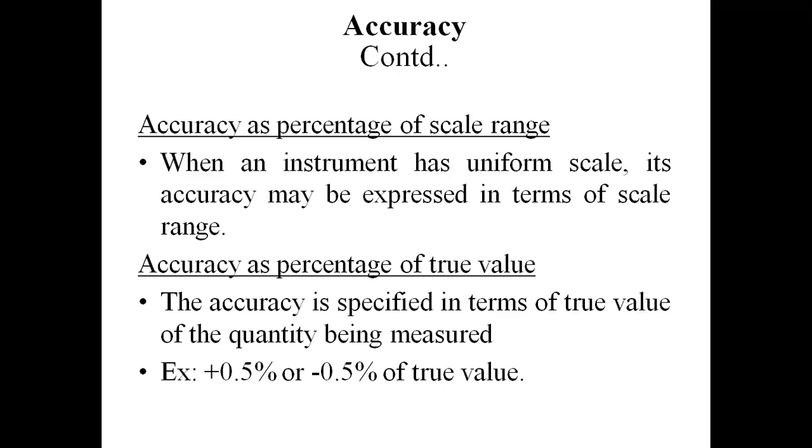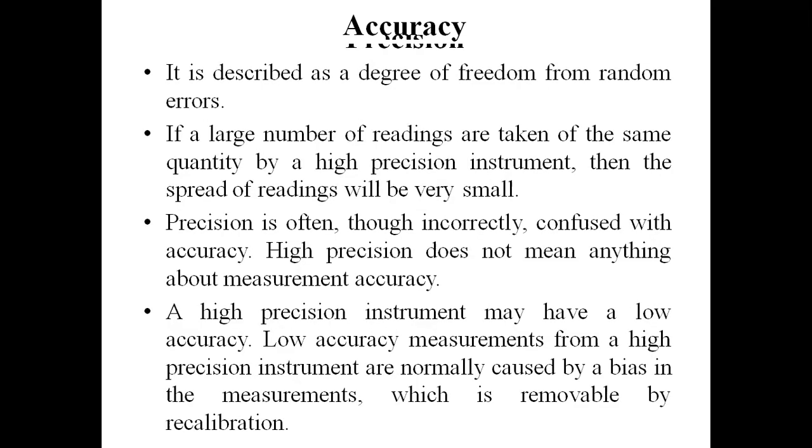Similarly, the accuracy can be specified in terms of the true value of the quantity being measured, for example plus or minus 0.5 percent of the true value.